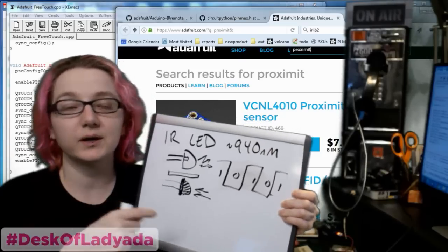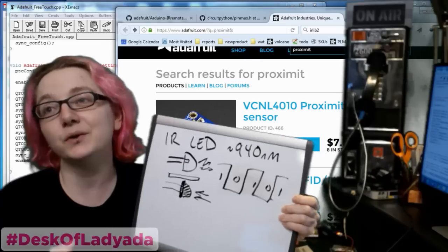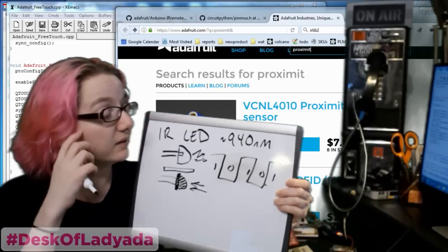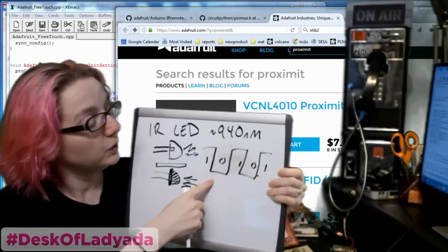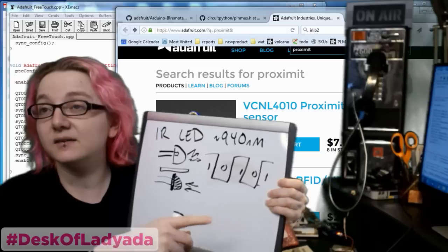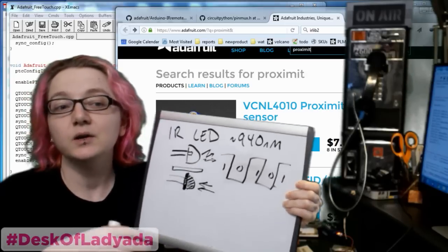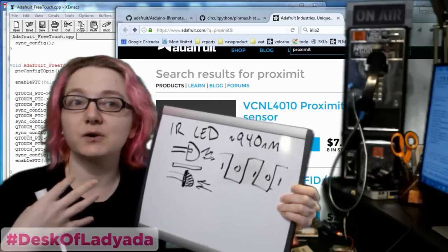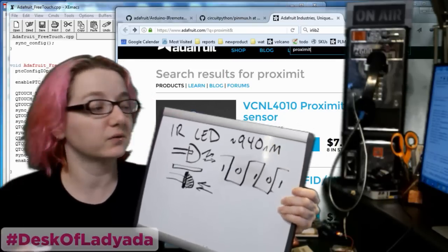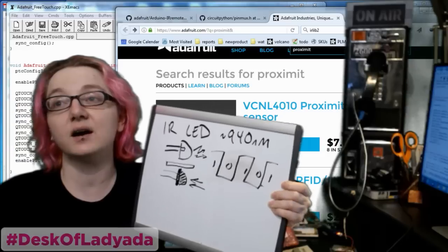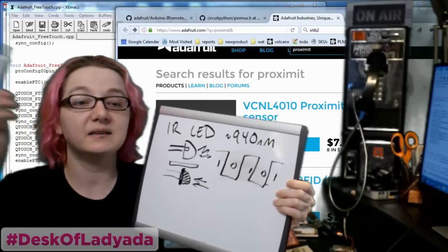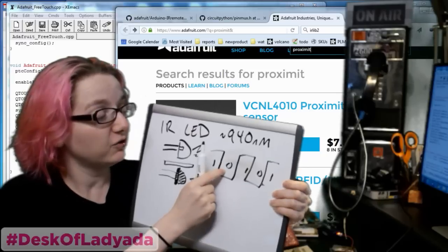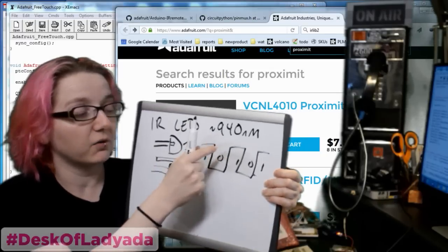That's one reason. And the second reason is that when you're just detecting if light is there or not, and you're only 4 inches away, like all these proximity sensors, these break beams, they only really work up to 6, maybe 12 inches away. They're not really meant for long distance. Once you want to do a long distance data transmission, you have to have some error correction, some way to filter it, some way to make sure that you don't have ambient noise in the way. Because right now, even though we can't see IR, there's IR all over the place coming from the LEDs, fluorescent lights, incandescent lights. They all emit IR, and so you can't just have the LED on or off.